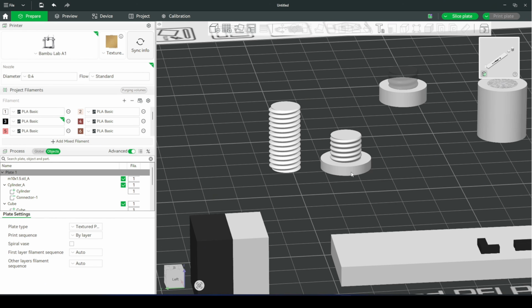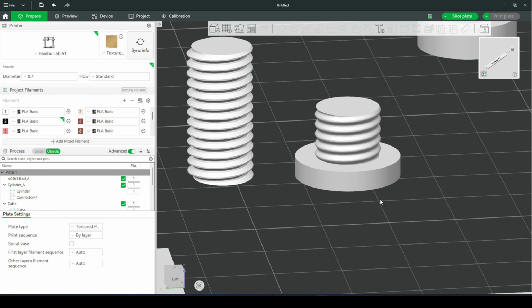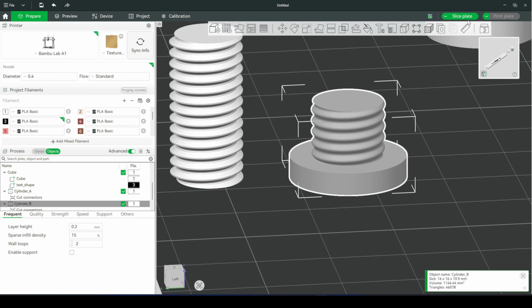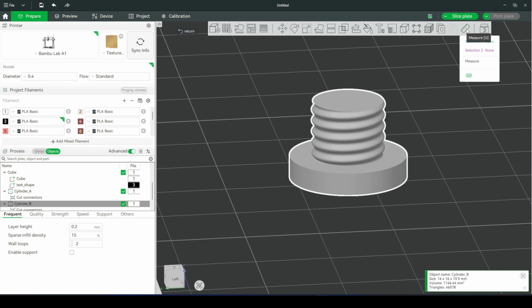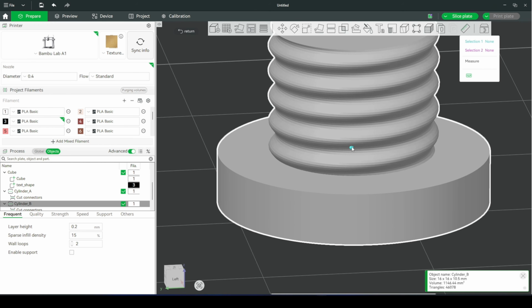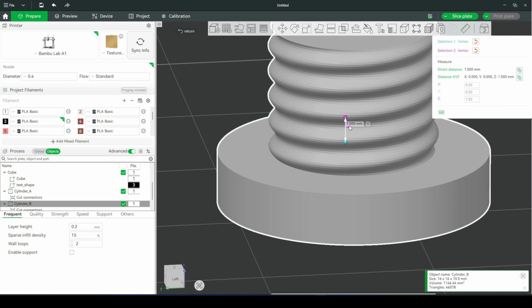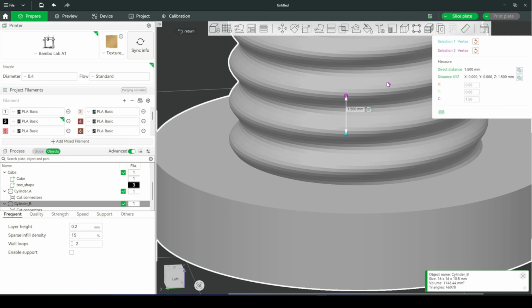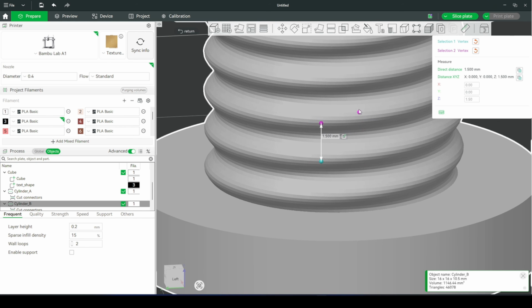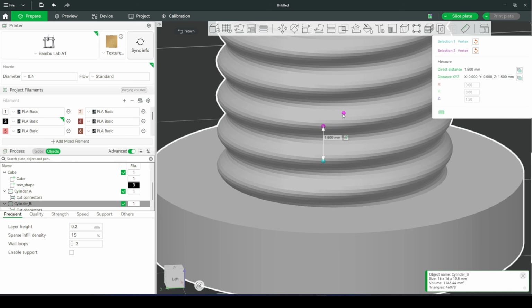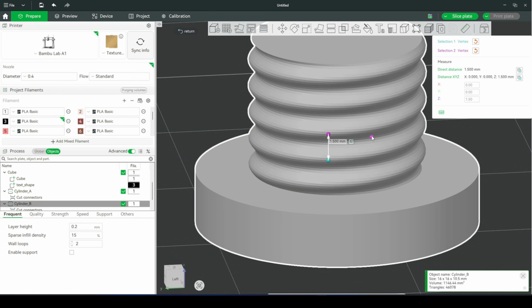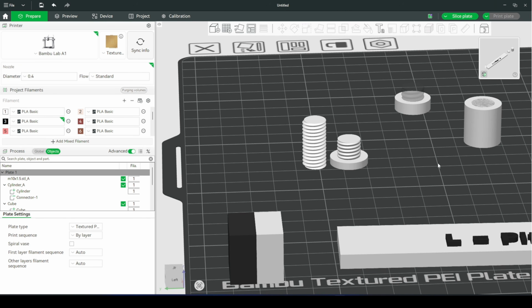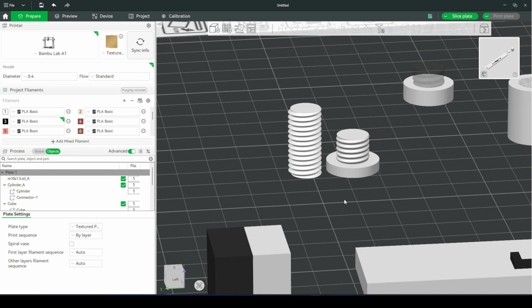All right, now for the moment of truth. Let's verify if our new thread pitch is finally compliant with the standard M10 blueprint. Let's click on the peak of the first thread. Click on the next peak and look at that. The result is exactly 1.5 millimeters. Our formula completely fixed the problem. The thread is now 100% accurate, standard compliant, and ready to roll. Everything is perfect and the pitch is completely standard.